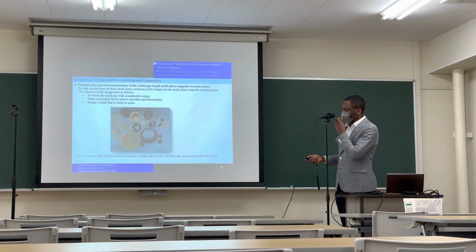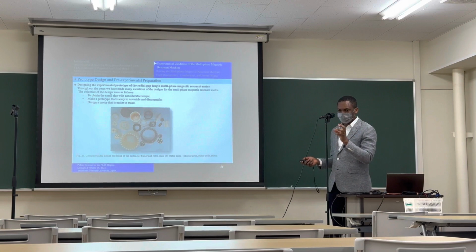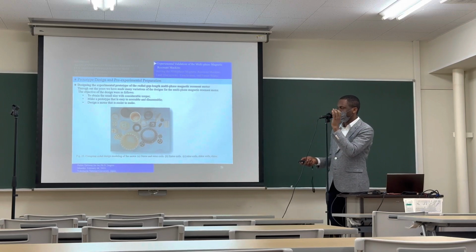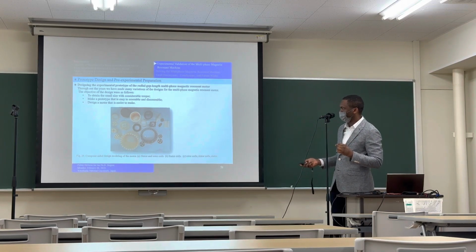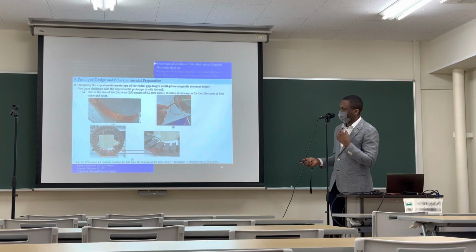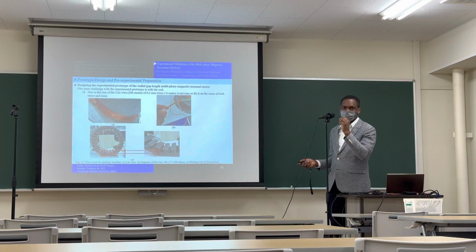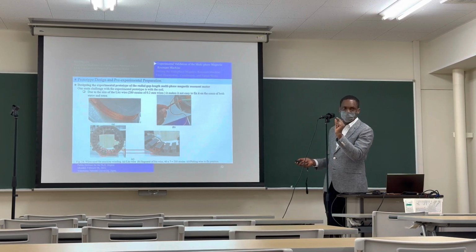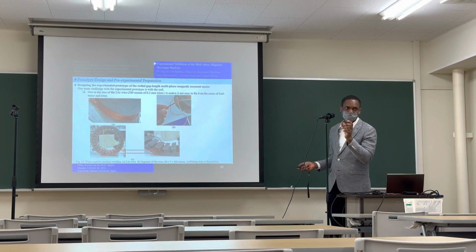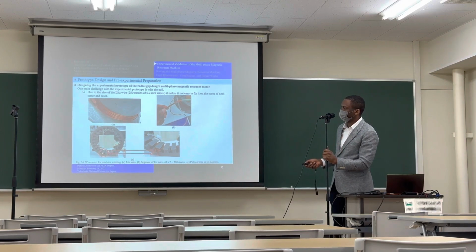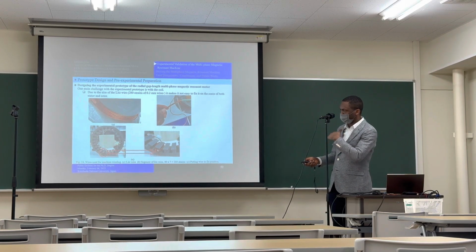Throughout the years we have tried to get the best possible design of this machine, more so because the coils that we want to use to wind the machine are very thick, and it's not easy to place the coils on the surface of the machine. This is the coil that we are using. We call it litz wire, and this one has 280 strands of 0.2 millimeter wire. So we have one wire of 0.2 millimeters, and this one has 280 of them. With the initial stator coil that we developed, we realized it's really difficult to wind it around this coil. So we had to look for a way to easily wind it, so we can put the coils in place.